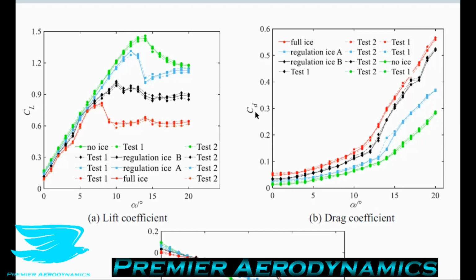But one thing I want to point out here, which brings me back to the functional device called tubercles, is remember how I mentioned that tubercles are very beneficial for stall, how they make stall softer. So stall usually happens very abruptly. Often a wing will stall and then it will experience a massive reduction in lift very suddenly over a very short range of angles of attack. However, with tubercles, this is extended, so you don't get nearly as severe a drop.